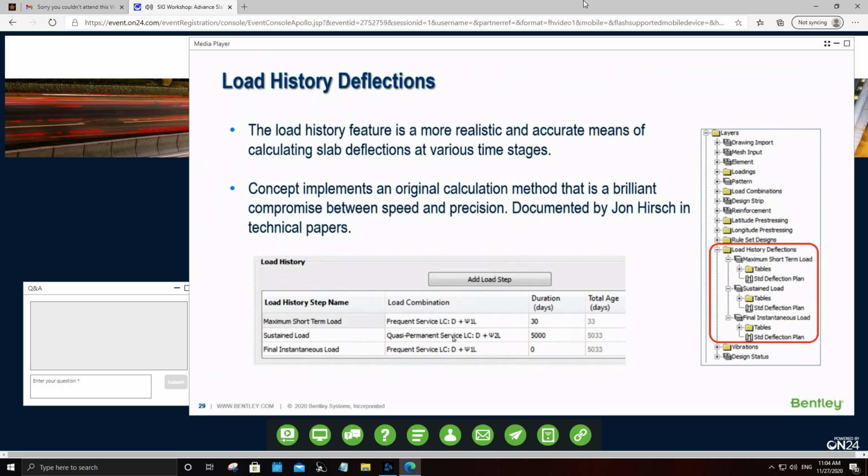So if you want more accurate results, I would recommend that you change the program reinforcements to user reinforcements and then do this analysis.